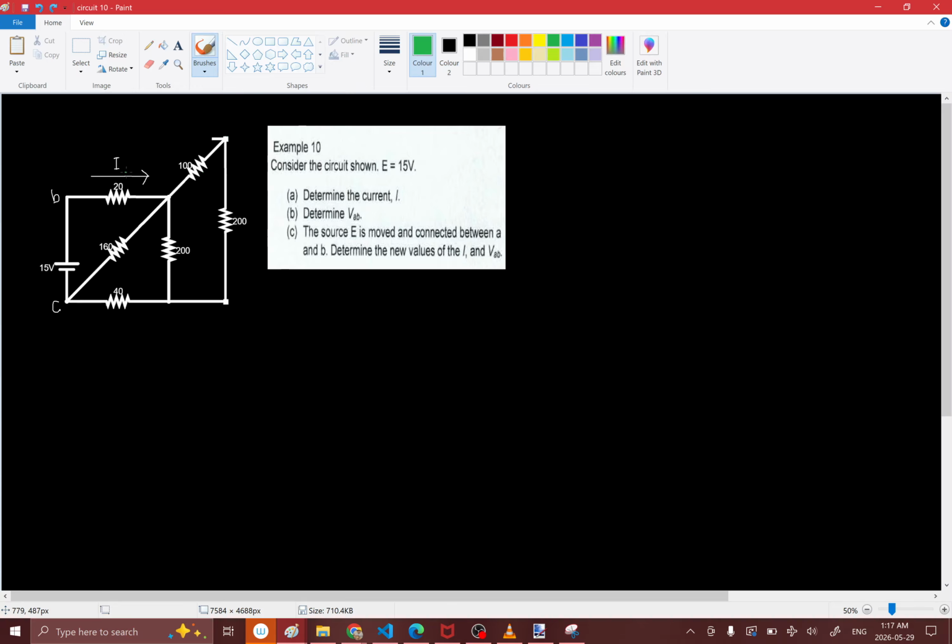Okay, so continuing on, it's the total current of the battery. Whenever a question asks you to find the total current of a battery, like the total current coming out of the battery, usually what that means is that they want you to find the total resistance of the path of the circuit, and using that you can figure out what the total current is going to be. So let me show you. First thing is, let's find R_T, total resistance.